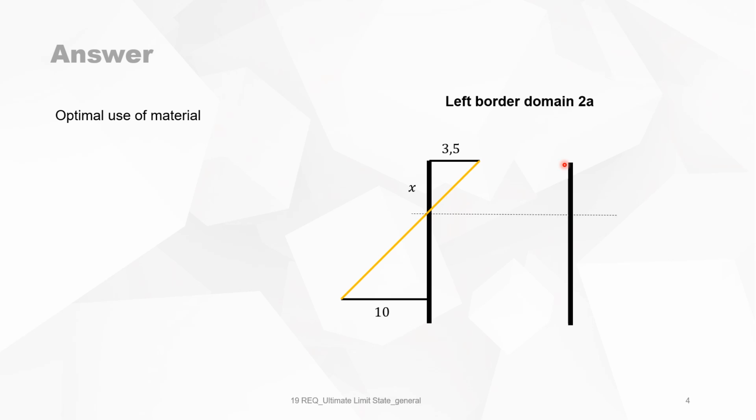Then we look at the stresses. Over the neutral axis, the compressive height of the concrete, we take the total value of the tensile force in the tensile reinforcement. Then we have the parabola-rectangular evolution of the stresses of the concrete, and when you integrate it, you get the total concrete compressive strength.